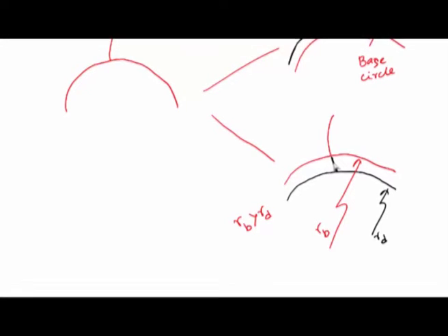So we make a very important observation which has major implications in our understanding of interference: the involute tooth profile can reside only in the portion beyond the base circle, not below it. If at all it is there, it is not involute.